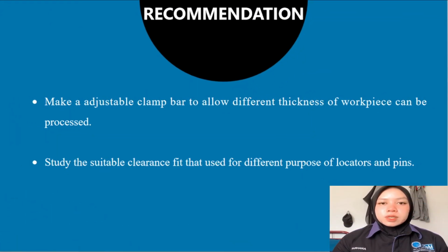Recommendations that we found after we finished the project. For the first one, make an adjustable clamp, so that if we want to change the part to a little bit bigger or smaller, we can still use the jig. Secondly, we need to study the suitable pin and locator that can be used on our part before we clamp it.